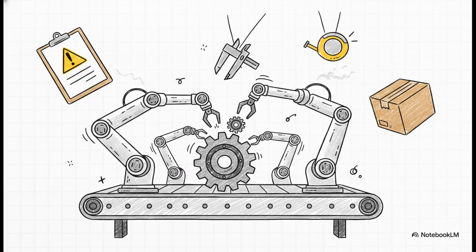And that brings us perfectly to phase 3, process design and development. Notice the big shift here. Phase 2 was all about designing the product itself, right? Well, phase 3 is about designing the factory floor process that will actually build that product. If phase 2 asked how the product could break, phase 3 asks how the assembly line could break. We're comprehensively developing a highly effective manufacturing system. The team creates a PFMEA, a process failure mode and effects analysis, to anticipate manufacturing errors. They also develop a pre-launch control plan, workstation instructions, and really map out how they'll measure success.